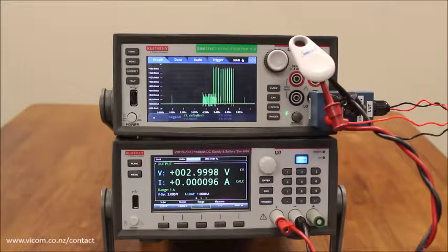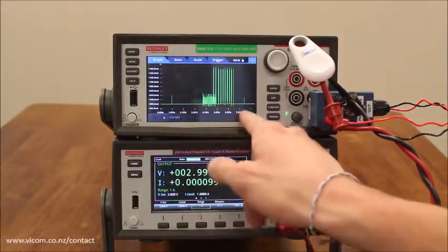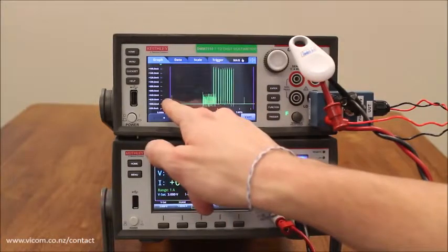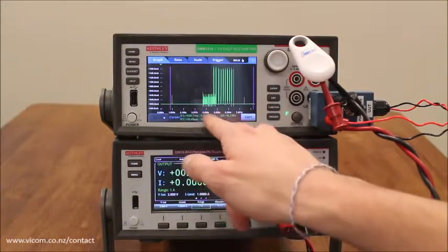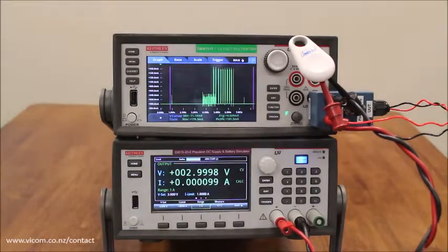Because the 7510 was able to capture all the various current values of this complex waveform, we can find the average current drawn from the power supply by swiping along the bottom of the screen to the cursors page, adding vertical cursors across the area of interest, then swiping back to vCursor stats, and giving us an average current of 4.869 milliamps.